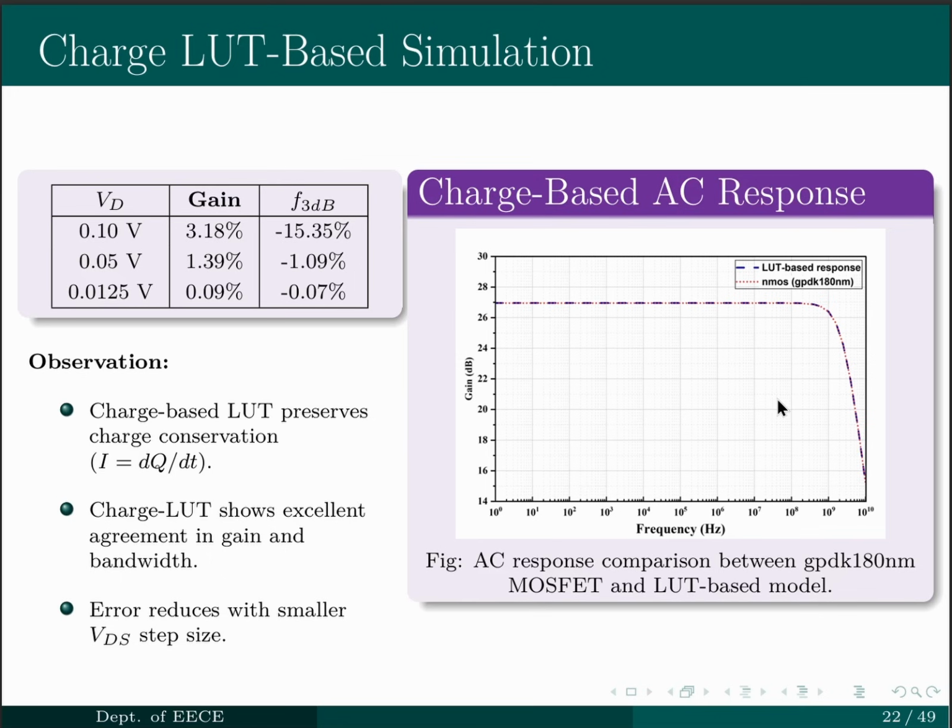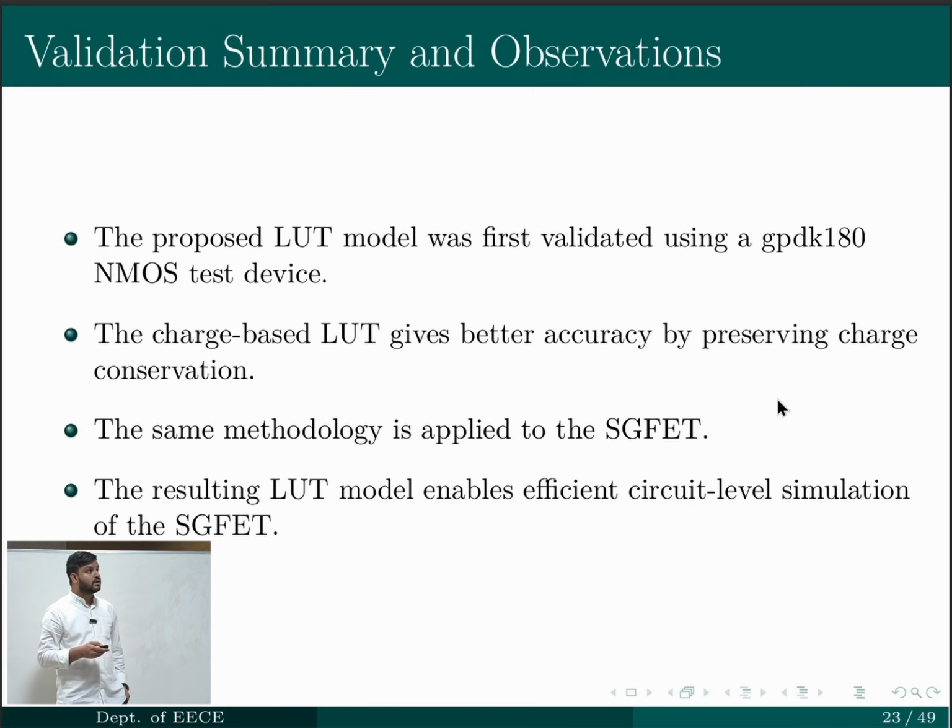From here we have validated that the charge based LUT is better, and now we are going to implement the proposed LUT model in the SGFET, which will also enable efficient circuit level simulation.